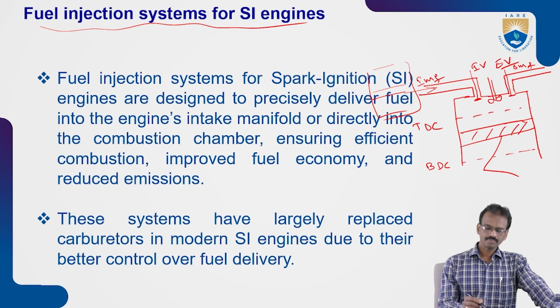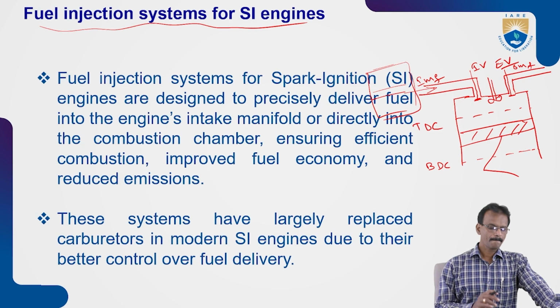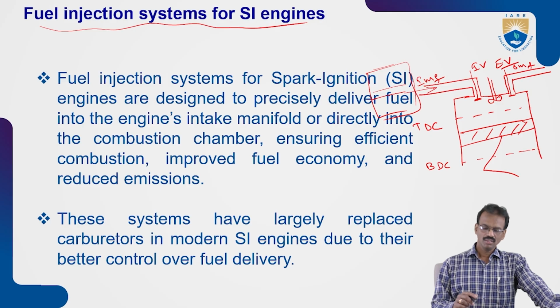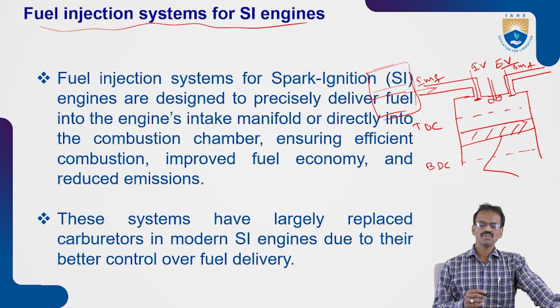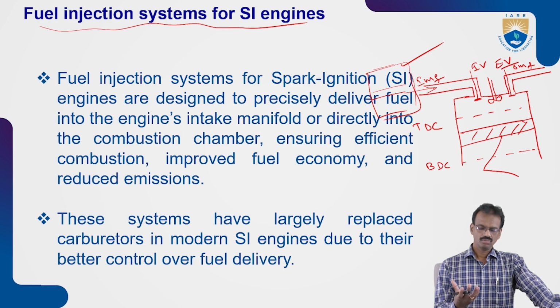We know this system, but nowadays fuel injection systems are being used in spark ignition engines, because there are some limitations for carburetors. The airflow is less because of the air which is taken through the orifice.